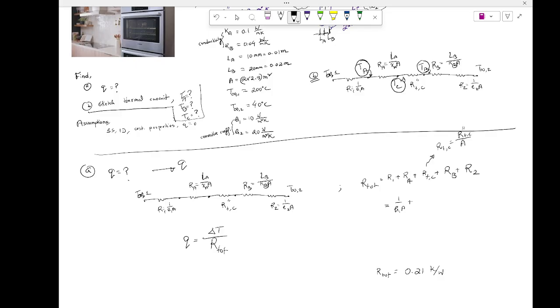Yeah, this is just one distance. That's the contact distance. See, there are 2 solids. In between those 2 solids, there are air layers. Because of the air layer, there is another resistance. That's called RTC, the contact resistance. That's the equation, the middle one, which means RTC. I wrote that equation, right? Did you see that? RTC double prime divided by A.